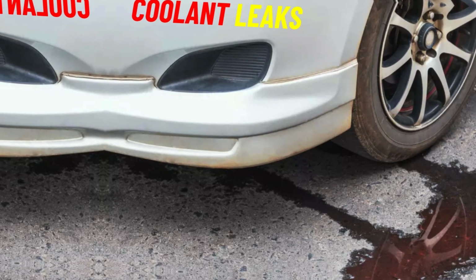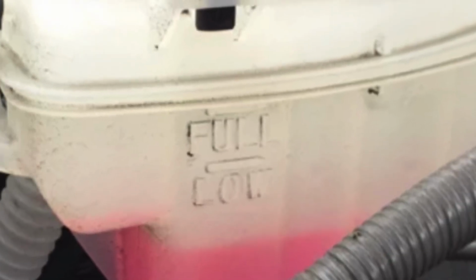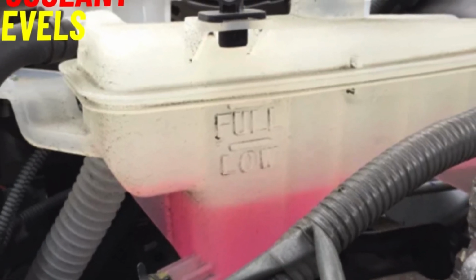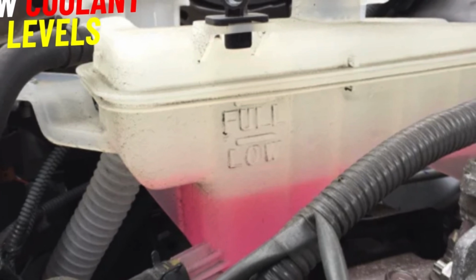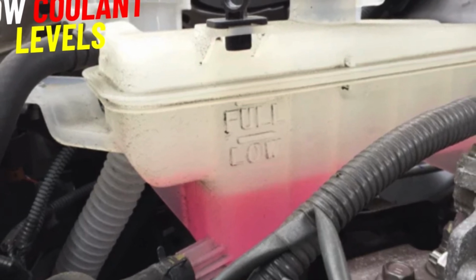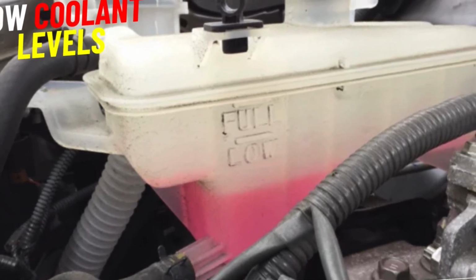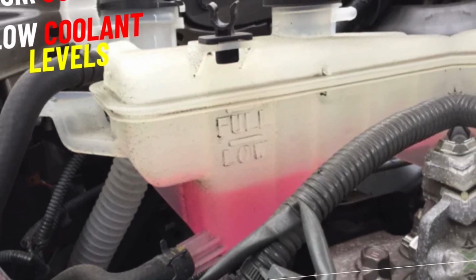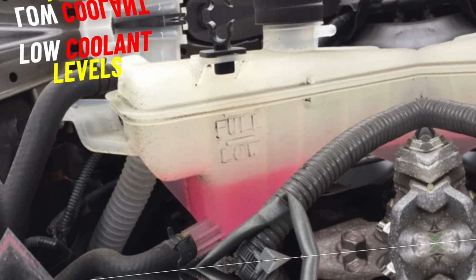Number 3. Low coolant levels. If you frequently find yourself needing to top up the coolant reservoir or notice the coolant level dropping without any visible leaks, it could indicate a problem with the radiator. A faulty radiator cap or internal leaks within the radiator could cause coolant to escape, leading to low coolant levels.